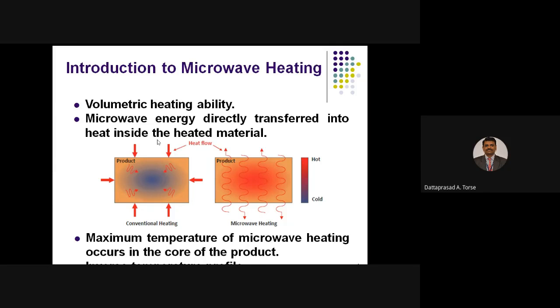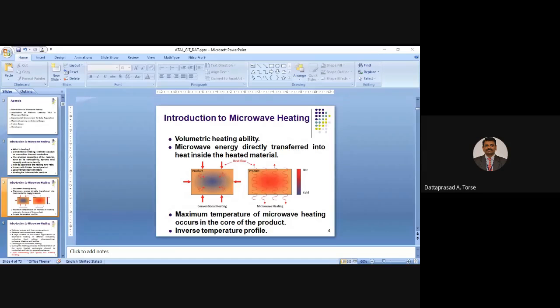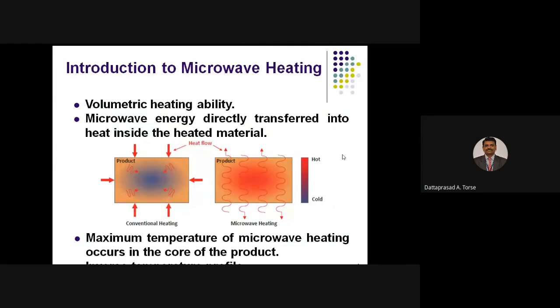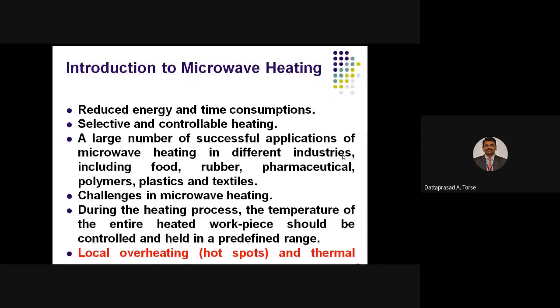One more very important point on why heating is important: every industry product that comes out, its quality depends on the heating profile that it has experienced. So how important microwave is in industrial applications, we can understand by looking at the quality of that particular product. I'll again be very fast here. The problem that we identified at that point of time was local overheating, or what we call a hotspot. Sometimes this hotspot results in thermal runaway.